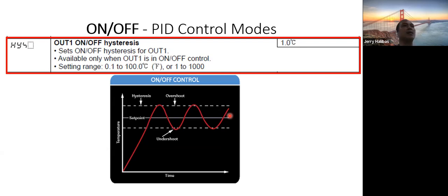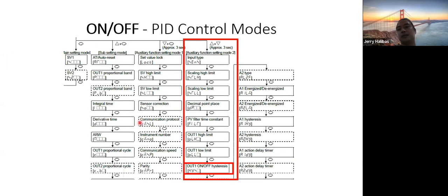But if you are using cooling systems for products, let's say it must maintain 1 degree, like the coconut water, Vita Coco, if you're familiar, that requires 1 degree. So it will be using a PID control system, because it must maintain 1 degree, unlike the typical flat iron or heater, which uses a thermostat on and off system. Then as I said, keep pressing the up or down on the Panasonic temperature controller until you see the hysteresis part.